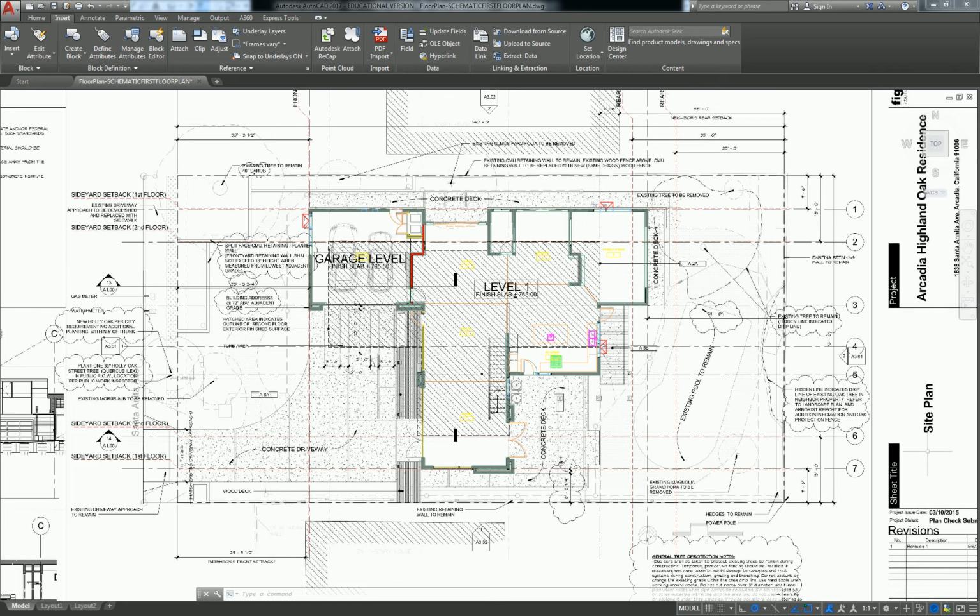So there's not much we have to do that you guys don't already know how to do. What I want to show you is really just how to manage this stuff. Generally speaking, I like to keep anything that's drawn into an AutoCAD file prefixed differently than what you would get out of Revit, for instance.